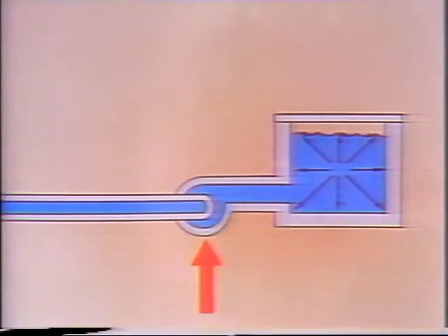An additional pressure can be exerted if the tank is sealed and pressurized with a pump. In this case, the additional pressure will be applied equally over every square inch of the tank. This means that the pressure in the tank will be the pressure from the pump plus the pressure exerted by the column of fluid inside the tank.